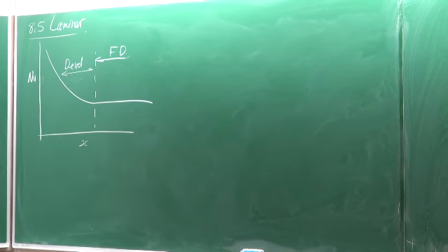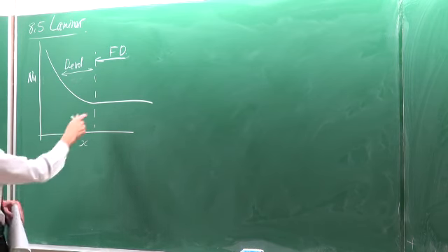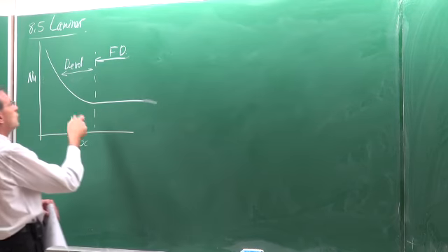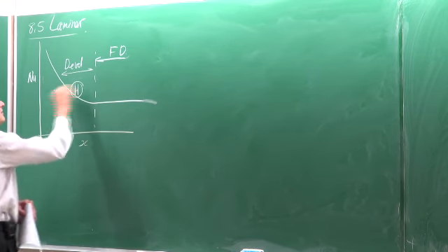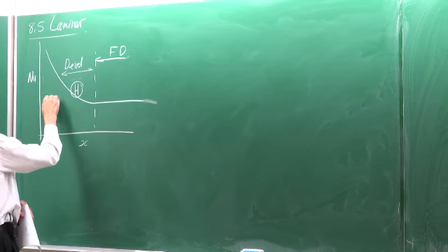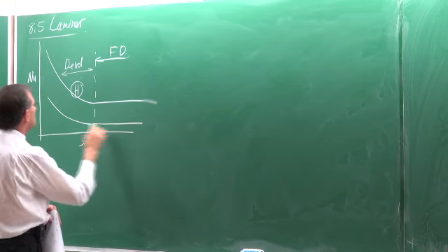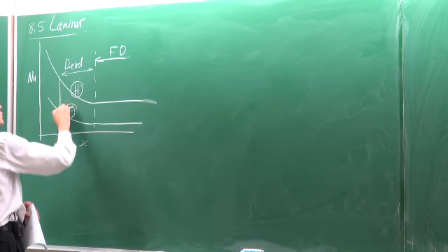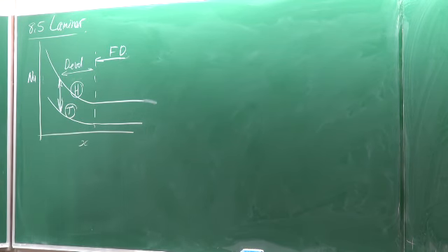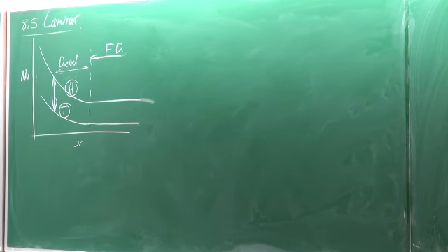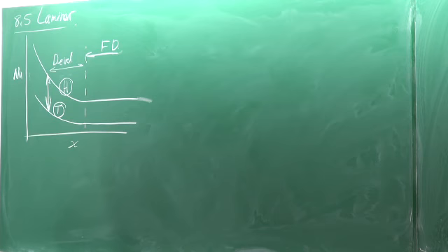Okay. Now, the method of heating or cooling is important. If I have a problem with a constant heat flux, then the results would be maybe like that. And if it's a constant wall temperature, the results would be like that. There will be quite a significant difference between the results for laminar flow. So we always have to remember that when we work with laminar flow problems. And it is always a judgment call that you need to make.